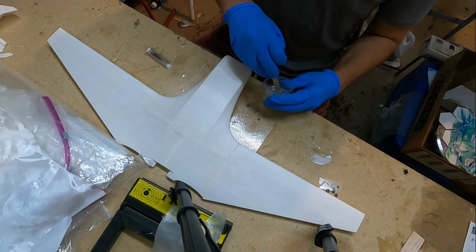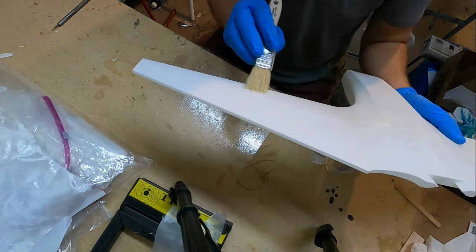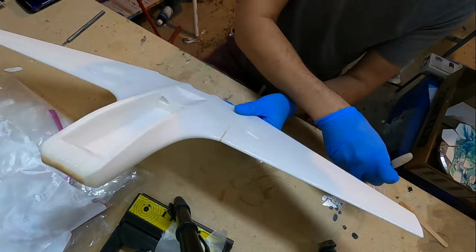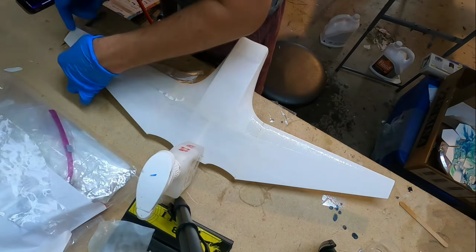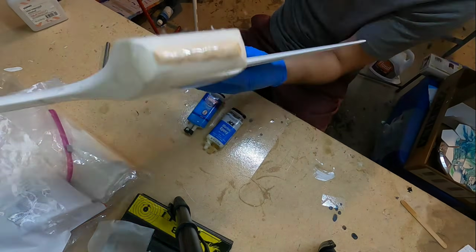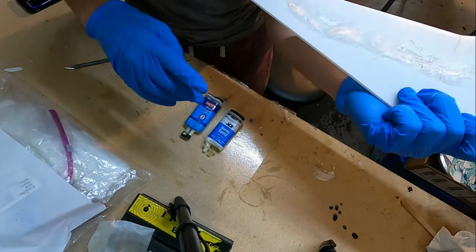I wanted to keep this build as light as possible. However, I did decide to add fiberglass reinforcement to select areas. 3D printed parts tend to fail by delamination between the layers, so I figured protecting certain areas would help keep the parts together during rough landings. Of course, all bets would still be off for a full-on crash with this plane.